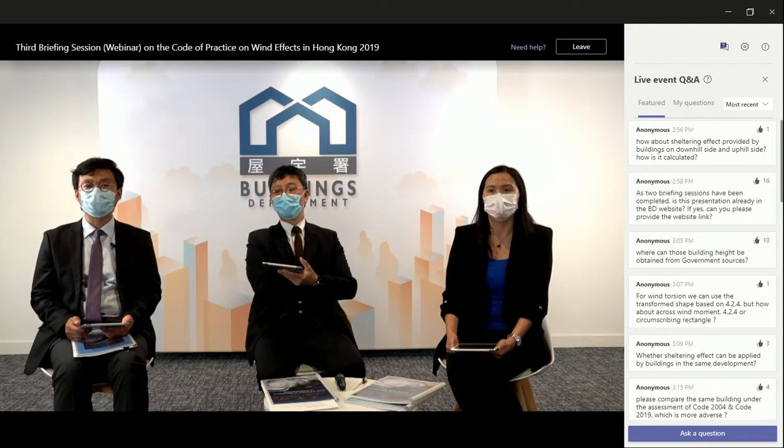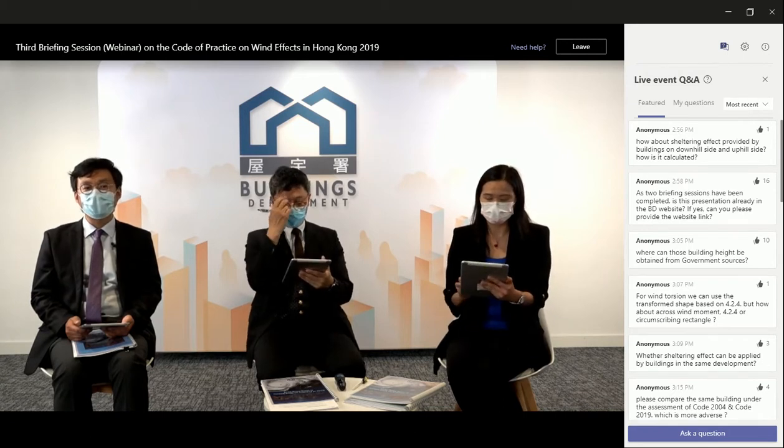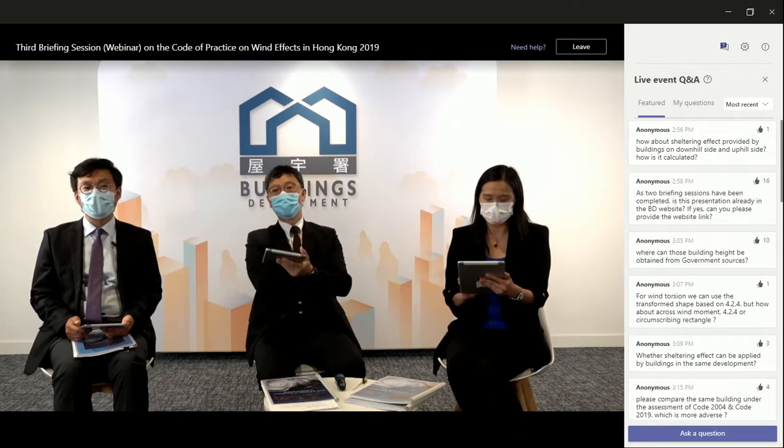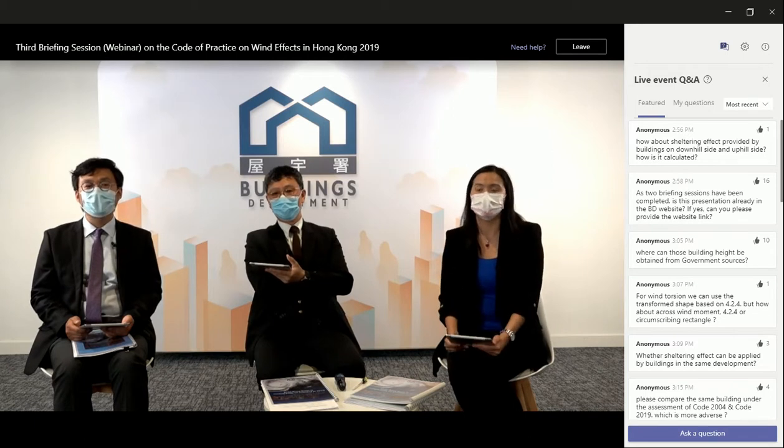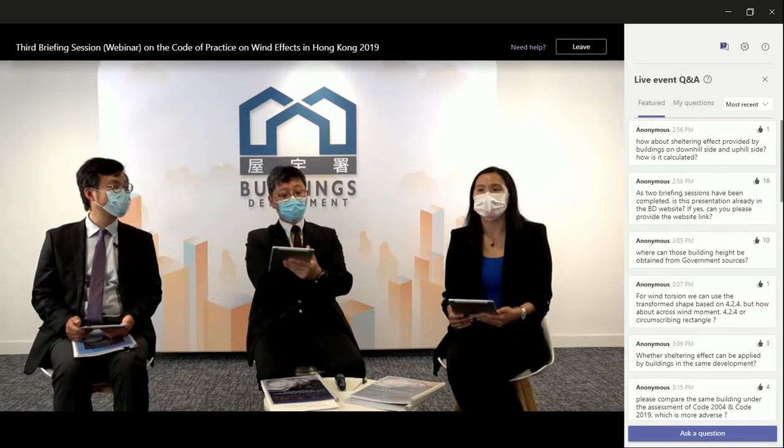And in the end, I want to further explain that for the twin towers, the condition will be slightly simpler compared with the multi-tower case, because for the twin towers we have only 2 towers. So for the critical torsional case generated by the partial load on the towers, we can consider 1 tower fully loaded and the other one unloaded. That will make the total load cases fewer than the multi-tower case. So for more details, please refer to the appendix in the EN. That's my answer.